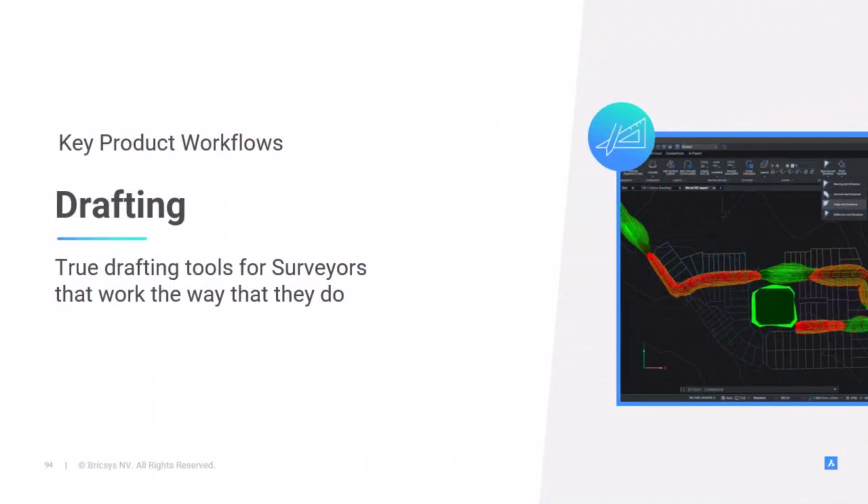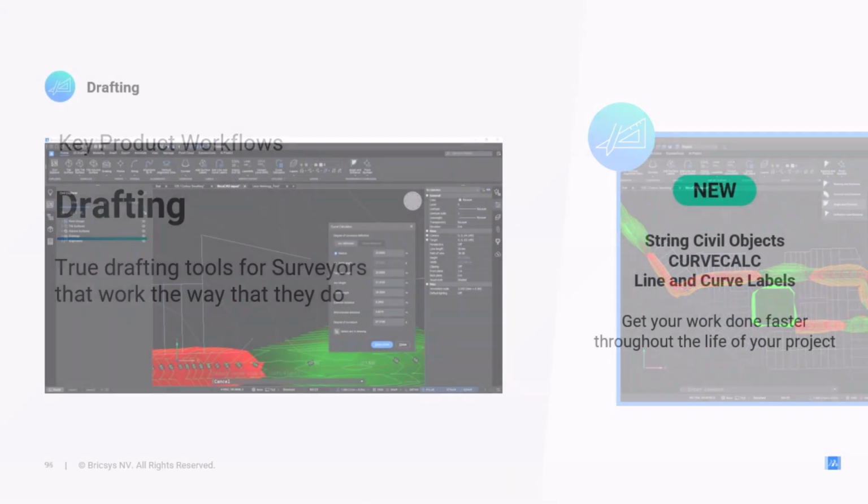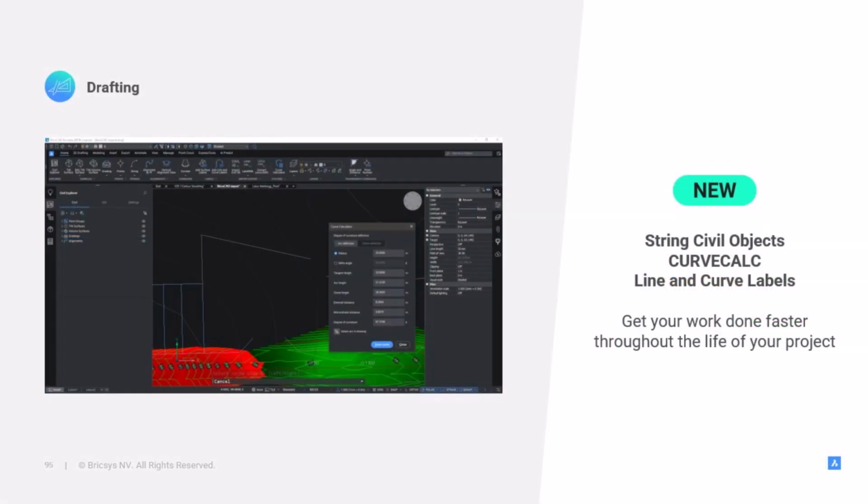Thank you, Linda. We've also been working to bring you drafting and annotation tools that work the way surveyors want and need to work. We already mentioned the new string object. From importing survey data to site grading and exporting data for construction staking, strings are going to get your work done faster throughout the life of your project. We've also added a curve calculator to save time and make survey drafting easier. And finally, we added line and curve labels to let you quickly and consistently label these features to your specifications.